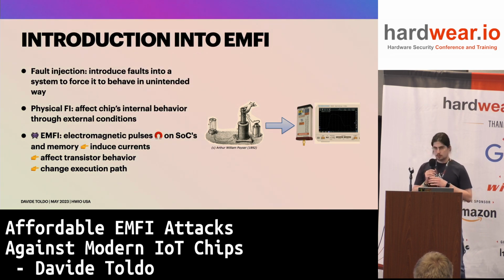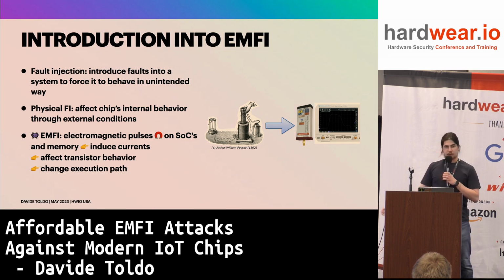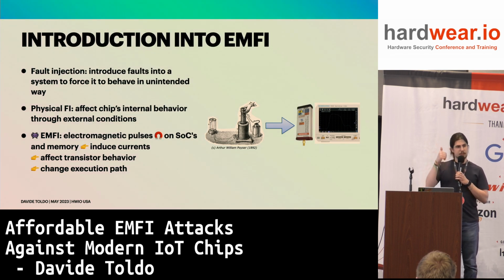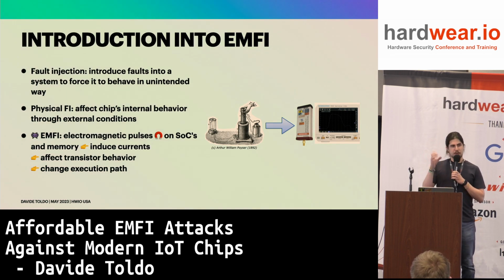In the picture, it's just a modern version of the experiment on the left. On the left you have a battery connected to a coil, which forms an electromagnet. Then, according to the right-hand rule, it forms a magnetic field in the z direction. And you move this electromagnetic field through another coil, and it induces enough current to power a lamp.